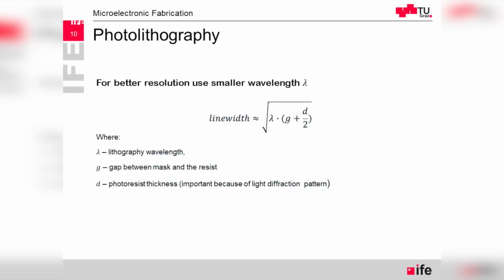The important topic in terms of photolithography is the resolution. It defines how small features we can produce on the wafer. And the line width is what we would like to be small, to have fine shapes. For example, the gate of the transistor. We can see that there are 3 contributors that all 3 have to be minimized in order to reduce the size of this line width.